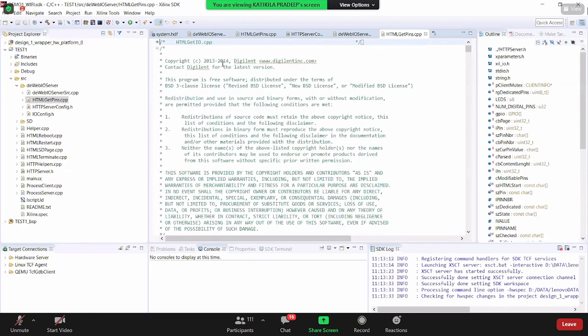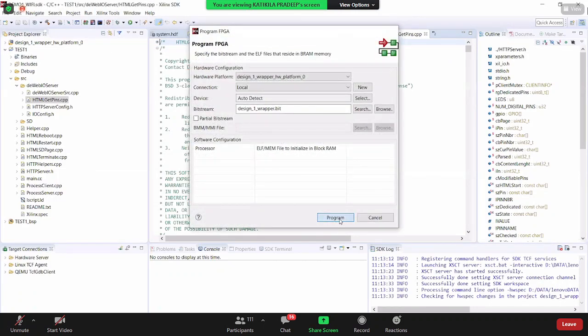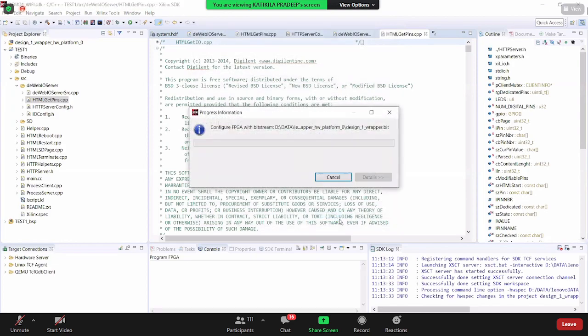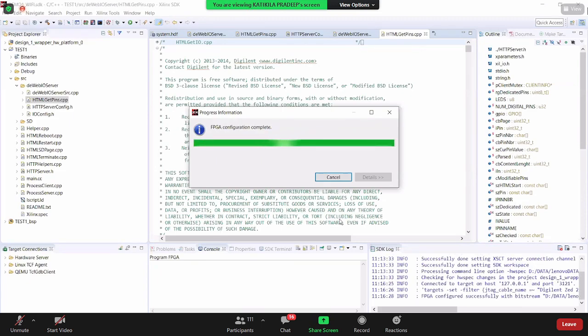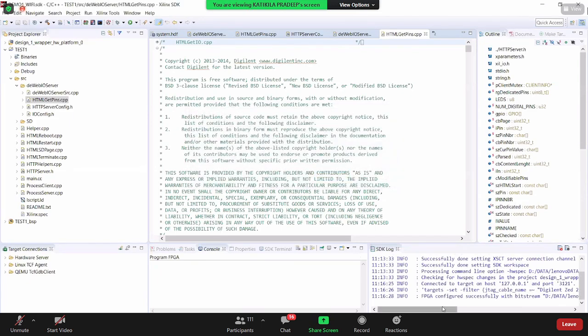So now I want to program the FPGA by using a JTAG cable and UART communication channel. I connected my FPGA to my PC, and while connecting this, I'm programming. This is my Xilinx toolbox, and I program the FPGA first. Click on Program Device. So it is programming. Yes, programming has been successful.